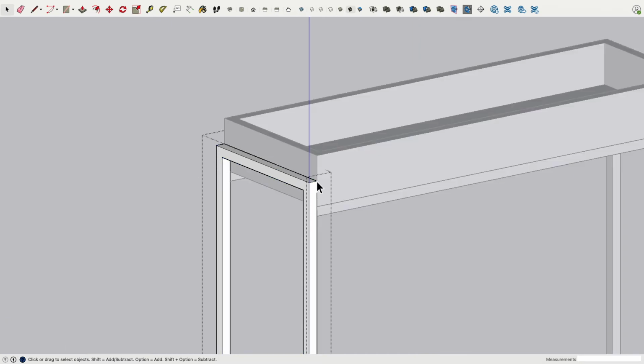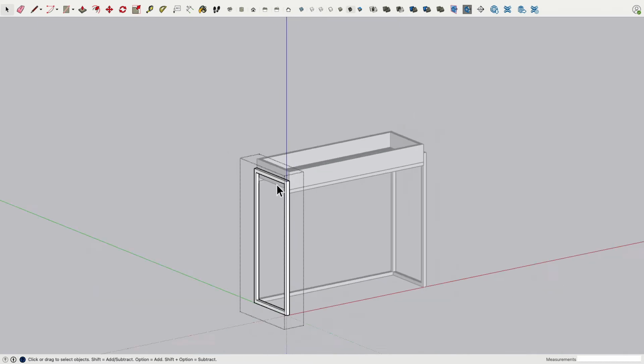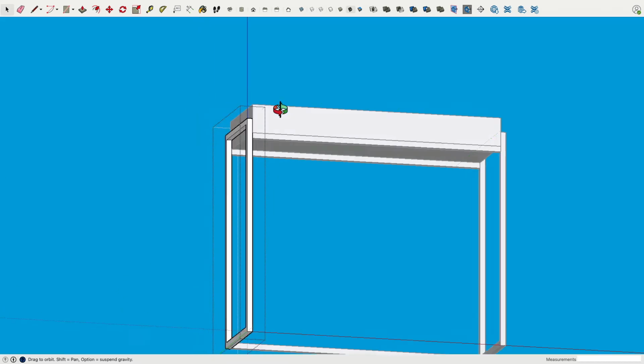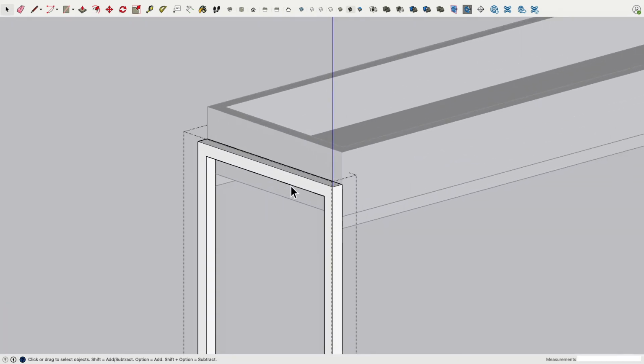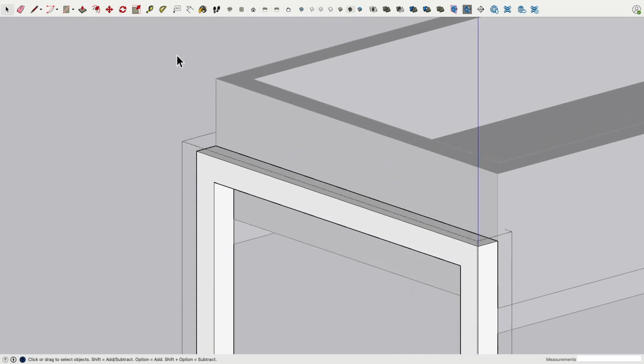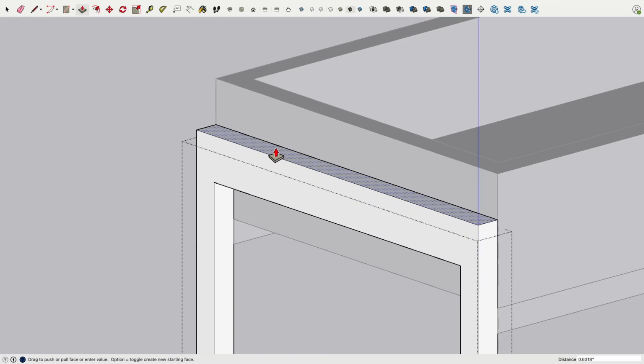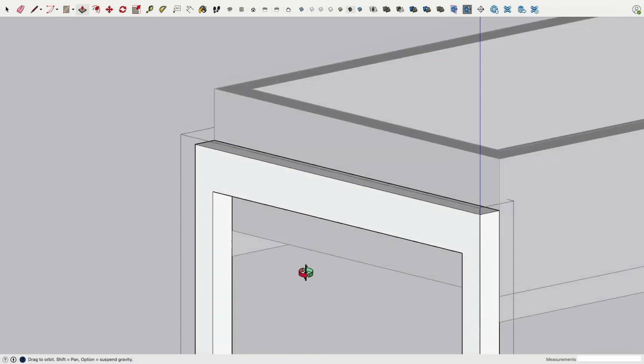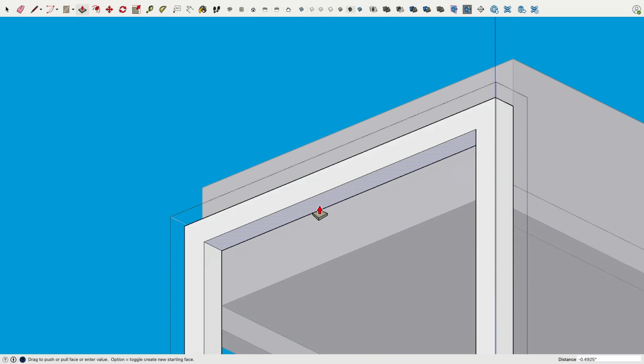You see now there is this dashed bounding box. I can see the geometry I'm focusing on. The rest is all grayed out. And now I can go to here, there, bring this up 0.5 and this 0.5 inches. Very good.